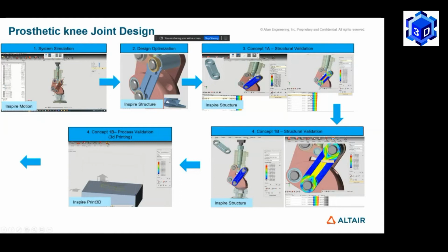So you see that excessive deformation is happening. If I go back over here, you'll see that after 3D printing, this guy is getting bent too much, and this bend might not be acceptable for you. If it is not acceptable, you may control it through the 3D printing parameters, or you may actually have to go back to your design stage itself.